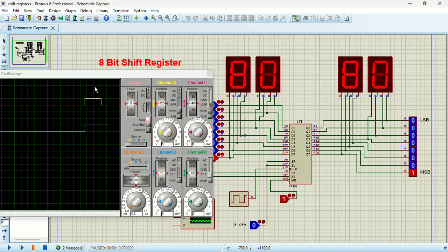After this section, after the parallel load of the data, as you can see, S1 now becomes zero. You see that, right? S1 now becomes zero, and S0 now becomes zero, and S1 is still going to be high. So now that means we have a mode switch; we were able to switch from one mode to another. This was the first mode, the parallel load mode, and in this section right here and going forth, we're now in the second mode, which is the shift right mode.